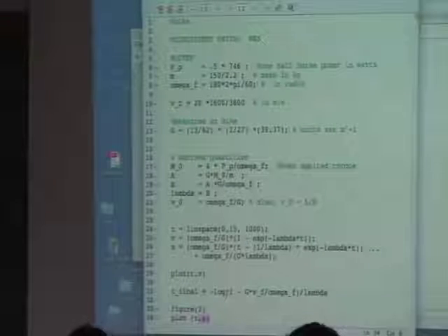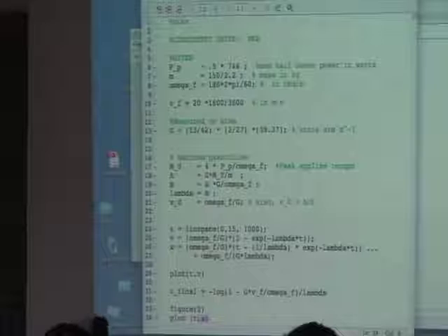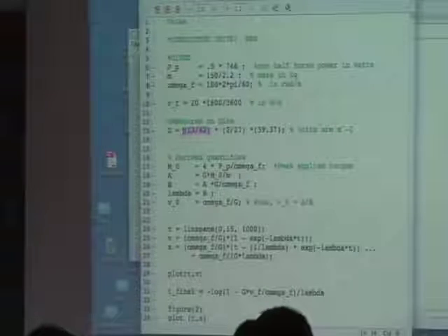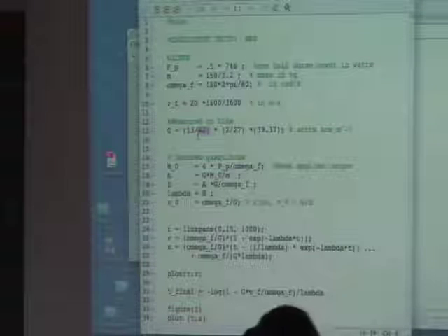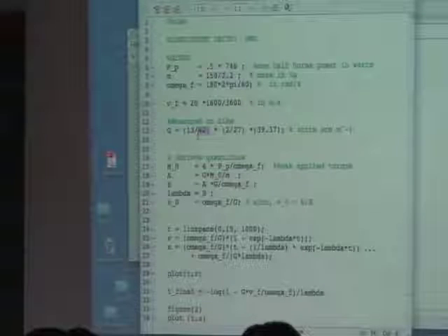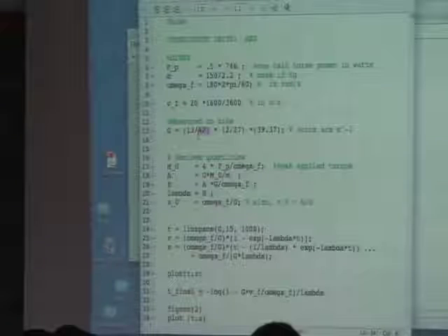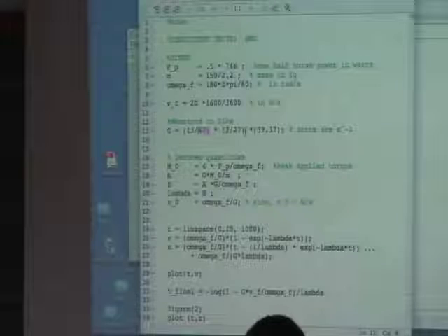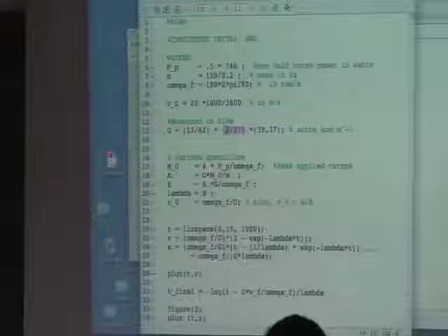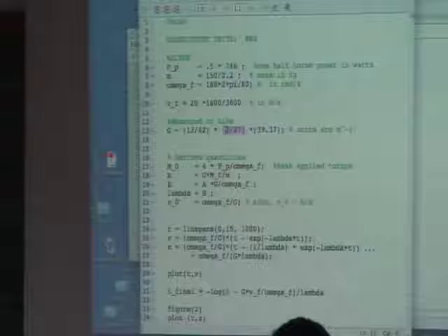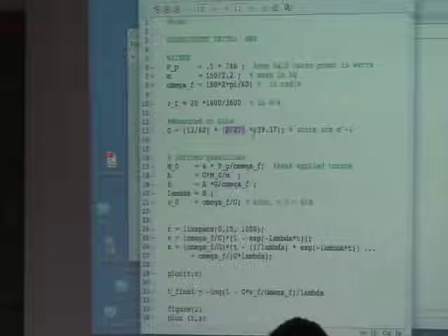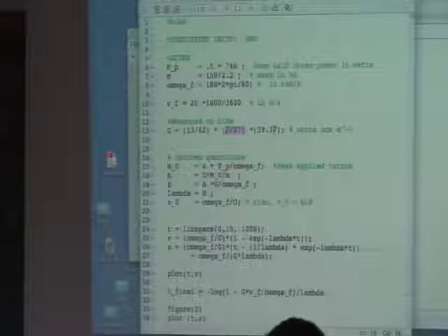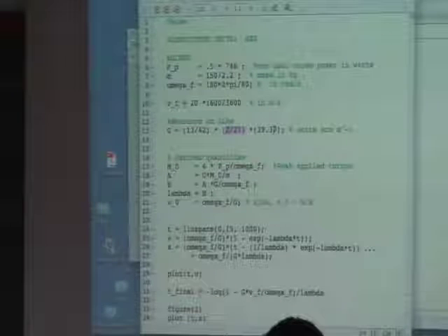Say again? What's the 2.7 and the 39.37? Okay, so this is the ratio of the number of teeth of the freewheel to the number of teeth in the chain wheel, and that ratio is also the ratio of the radii of those two. The third quantity is the radius of the rear wheel, R sub W, which was on the bottom of the fraction. So that's 1 over 27 divided by 2 in inches, because it's a 27-inch wheel, which means 27-inch diameter. Then we have to multiply by 39.37 inches per meter to get the inches to cancel and get the answer in reciprocal meters.